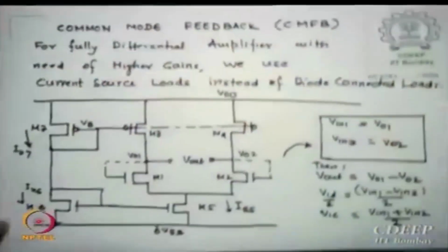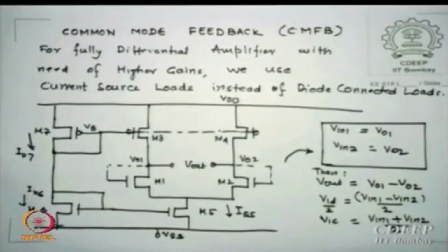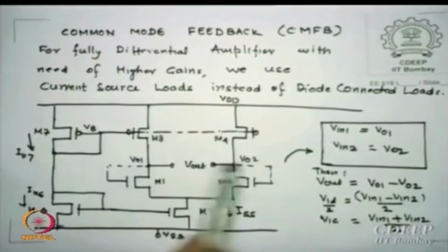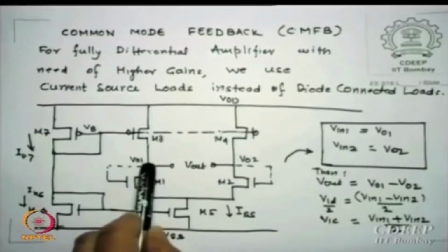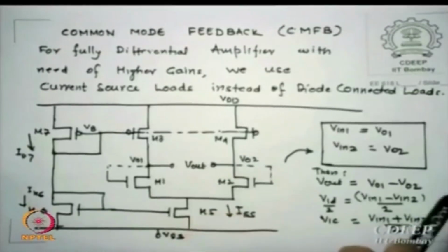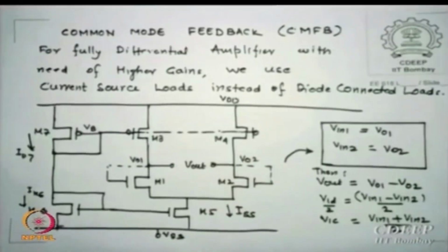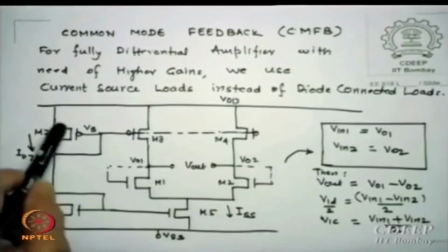We keep saying to maintain a good common mode voltage, we have said that normally fully differential systems are used for higher gains. Now, this is your standard double-ended op-amp, with one output VO1 and the other VO2. To make it simpler to understand, I have connected the output of this to the input of this. In the normal case there would be a resistance R from output to input, but right now I chose R to be such that the feedback can be negative feedback, differential feedback. So this is a differential feedback which I kept, and this is your bias circuit.